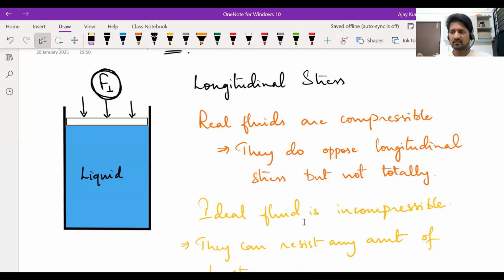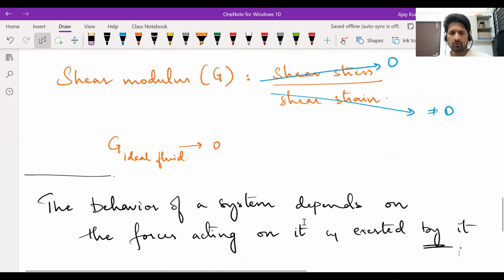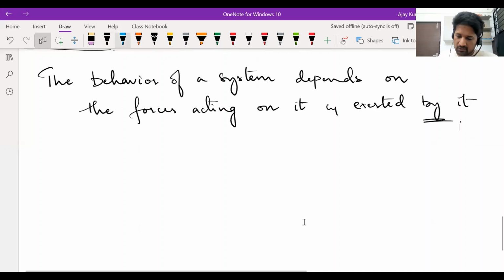Pressure basically makes the molecules want to escape from that place. Greater the pressure, greater their tendency to escape from there, so greater the forces they will exert. So the force exerted by a fluid depends on the pressure of the fluid. So the first thing you need to know if you want to deal with fluid systems is how to calculate pressure in a fluid.